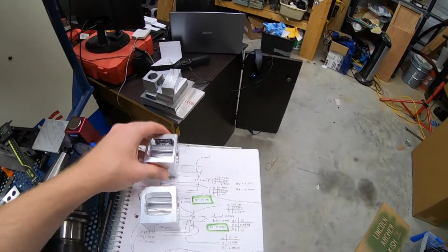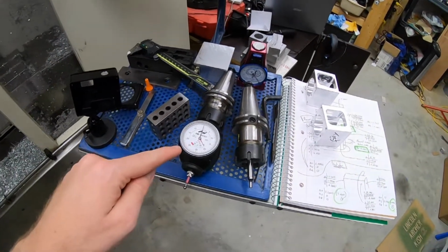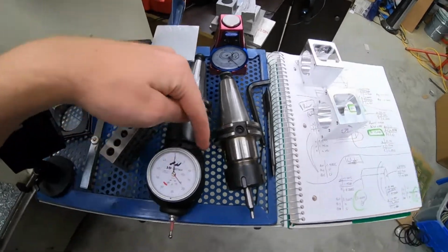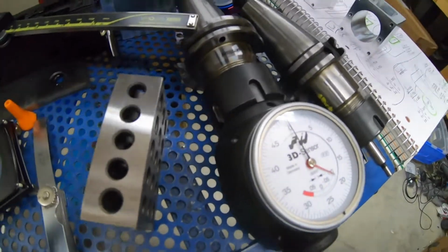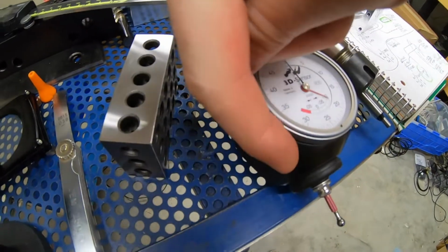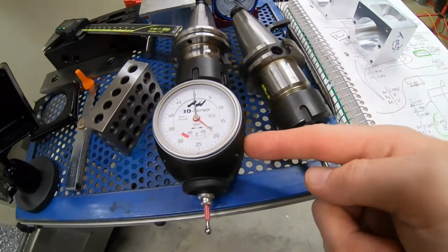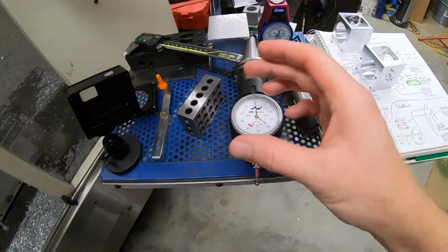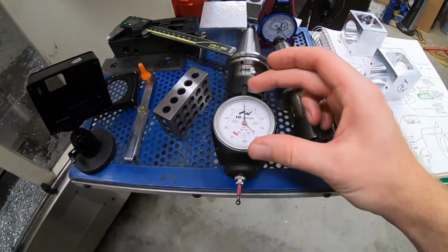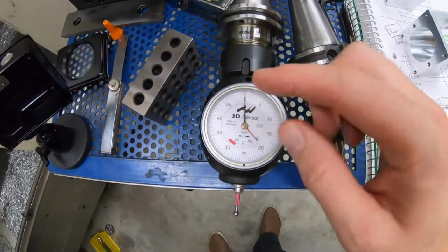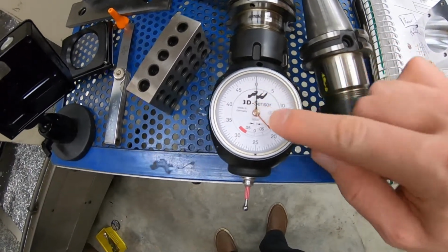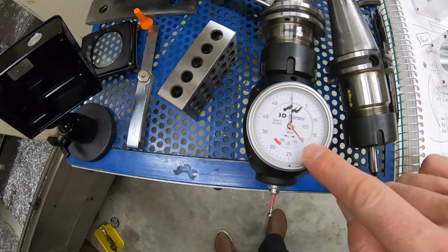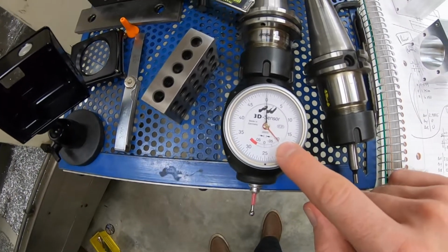So that was the first thing I did. I fixed that. So I used these. There's 4 set screws around this face. I don't know if you can really see it, but there's one here, one over here, and then 2 over here. And so I used those and then rearranged this guy to where it read 0 with the black arm, and then this guy, the red arm, was right at the -100th thou mark.